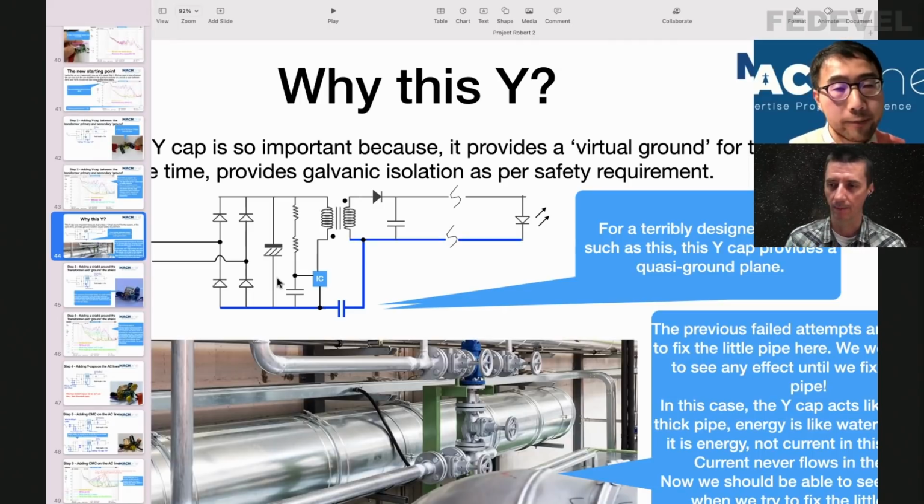So basically, this 1.9 meter cable suddenly will have some kind of ground, but before it was not really ground. Yes, I think this is a good understanding of it. Before, that cable was an antenna, and the noise source is this big voltage difference between here. But now you have a capacitance, and then you basically reduce that noise source.